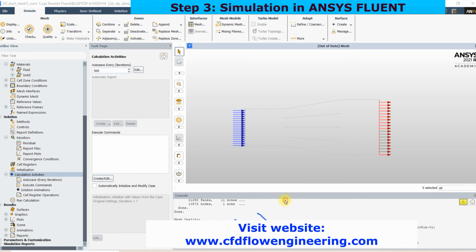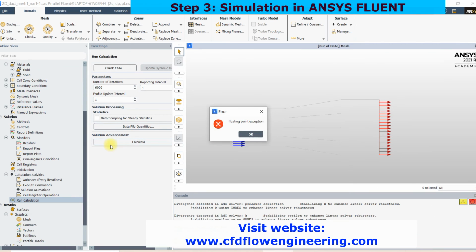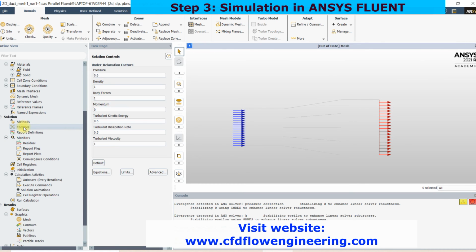It has 0.9865 orthogonal quality. That means very good mesh quality, which means convergence will be better. Then click here, give some 6000 iterations and run it. Here a floating point error occurred. That means some issue is there.